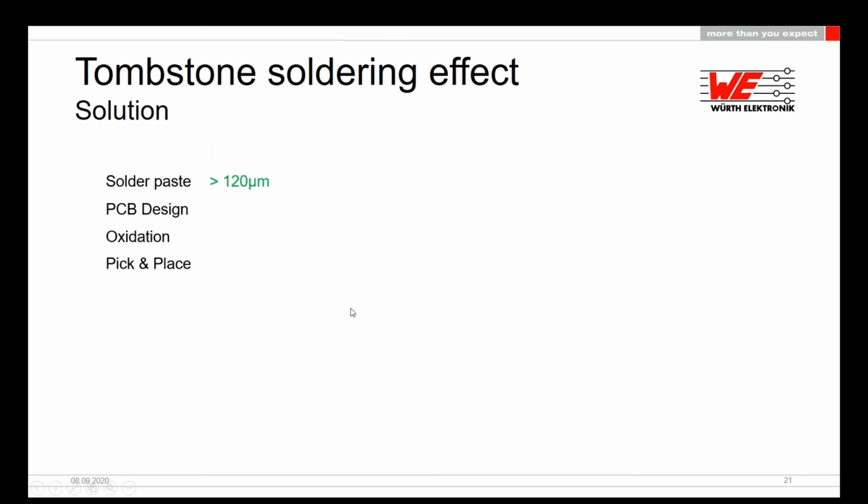And the last topic, by reflow. Please keep the ramp-up temperature at preheat of the reflow profile under 3 Celsius degrees per second. And please refer to the Würth Elektronik reflow profile for SMT LED, which is according to the standard JEDEC 20E in our datasheet.